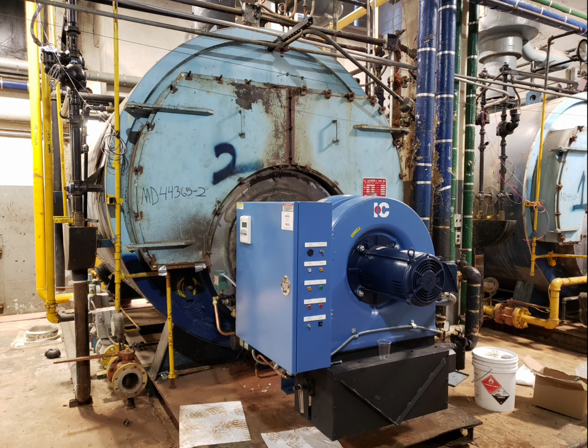And the pre-purge, what it does is when a vapor stat, because these boilers have vapor stats on top of them instead of pressure controls, kicks back in at about, let's say, 4 psi, 3 psi, the burner does not immediately initiate a flame. The burner will run on pre-purge for at least a minute, depending on what kind of relay you have inside of this box over here.